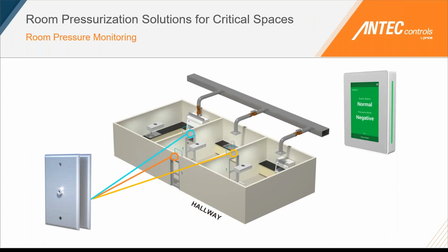So in this application, again the same pharmacy application, we have our pressure display, and we have our pressure sensor giving us that differential pressure across the doorways. Typically you may see a pressure monitor installed at each doorway. Each monitor is just measuring one differential pressure zone, and it's giving us a feedback mechanism before the facility staff enters into that space.